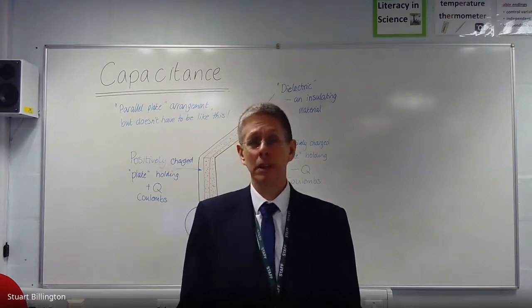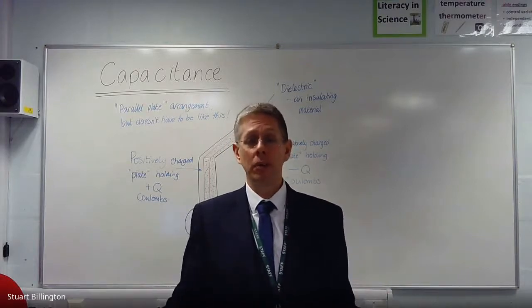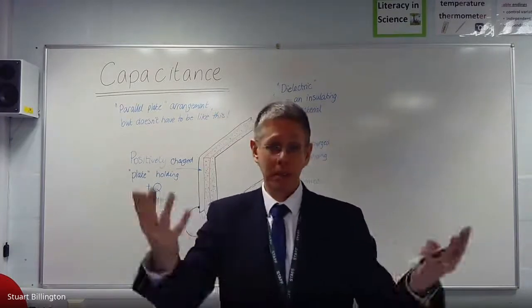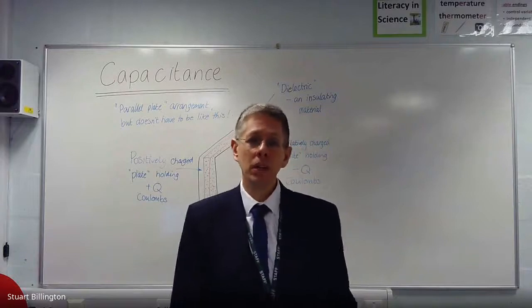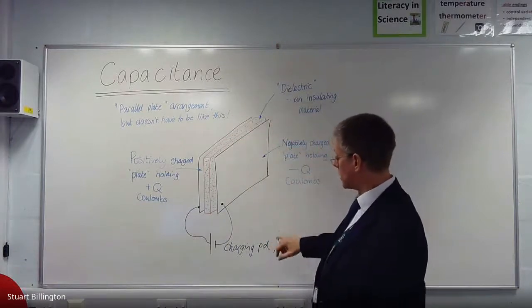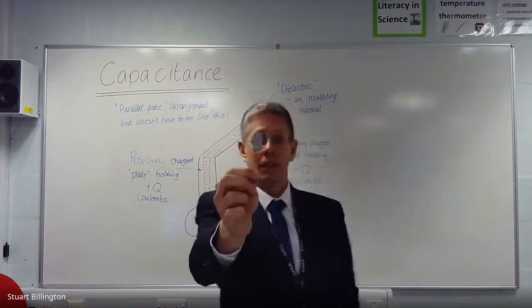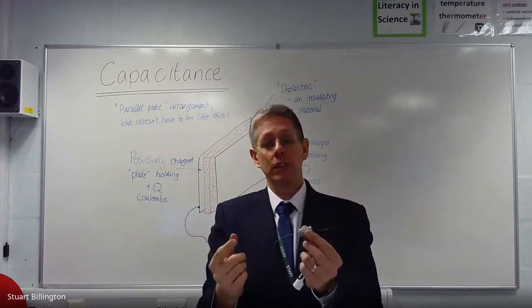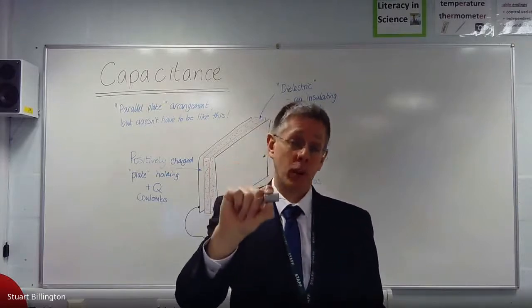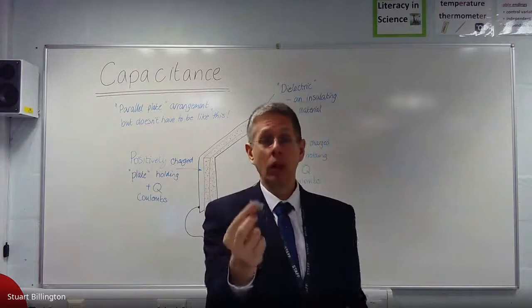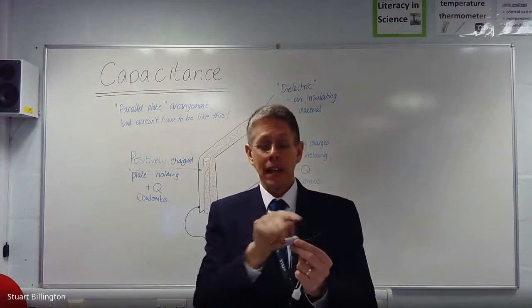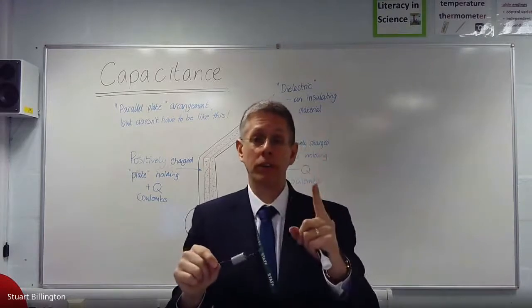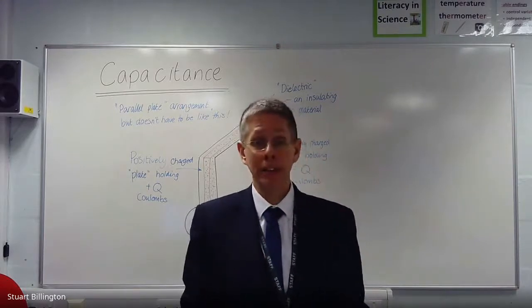We just said it was going to be the mass per unit volume because it was just an arbitrary choice, but we liked the number 1 because it made all our sums nice and easy. So we're going to do a similar thing now, and we're going to say, if I give you a capacitor and you don't know what its capacitance is, then what you just need to do is attach it to 1 volt. Just attach it to a power pack at 1 volt and then test how much charge is on it.